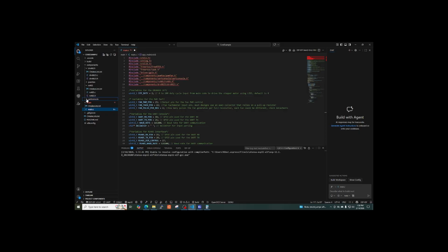Even if we power it down and have to resume, we can read the non-volatile storage and then resume the cycle count, and every so often update the non-volatile storage. We'll have to figure out a time frame for that, because I don't know if updating the non-volatile storage for every increment will hurt it. So while I'm thinking about stuff, let me